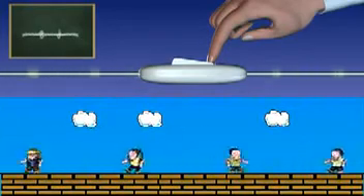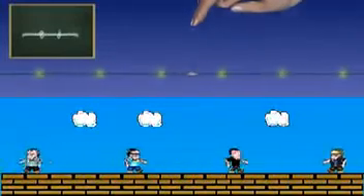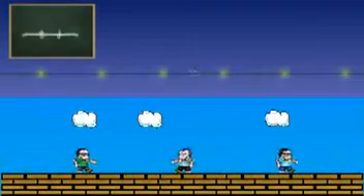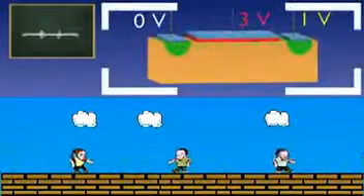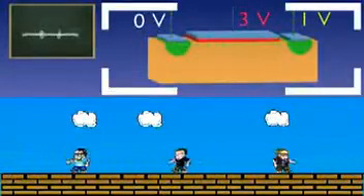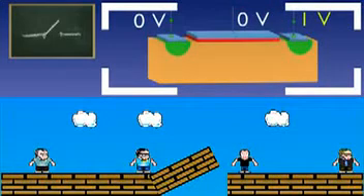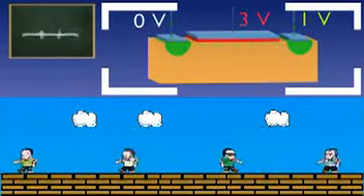In order to store and manage huge amounts of information in the least space, these switches need to be manufactured as small as possible. A microchip can contain billions of them. However, tiny as they are, they still have to work as electrical switches. There must be a path for the electrical charge to flow, and some electrical mechanism that will allow or prevent the flow of this current. This minute switch is the MOSFET.